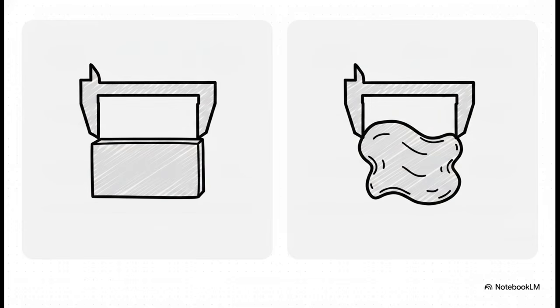And that's because basic size limits just check the local distance between two opposing points. You can take a micrometer to the valleys and peaks of that wavy block, and as long as that local distance is within tolerance, it technically passes size inspection. So size limits alone absolutely do not perfectly control a part's overall shape.